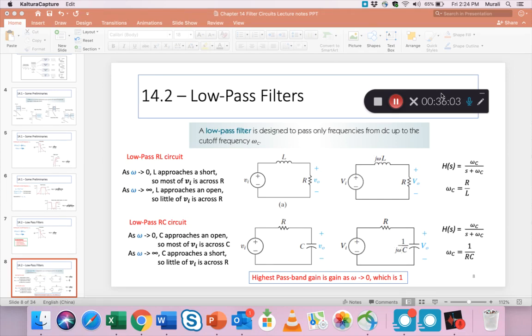But at very high frequencies, the capacitive reactance falls so much that most of the IR drop, the voltage drop, appears across the resistor. And you're not looking at the resistor in this case. You're looking at the capacitor, right, to see what the voltage is. And you'll notice that less and less of the voltage of the high frequency components, whatever the high frequency magnitude is, starts to show across the capacitance.